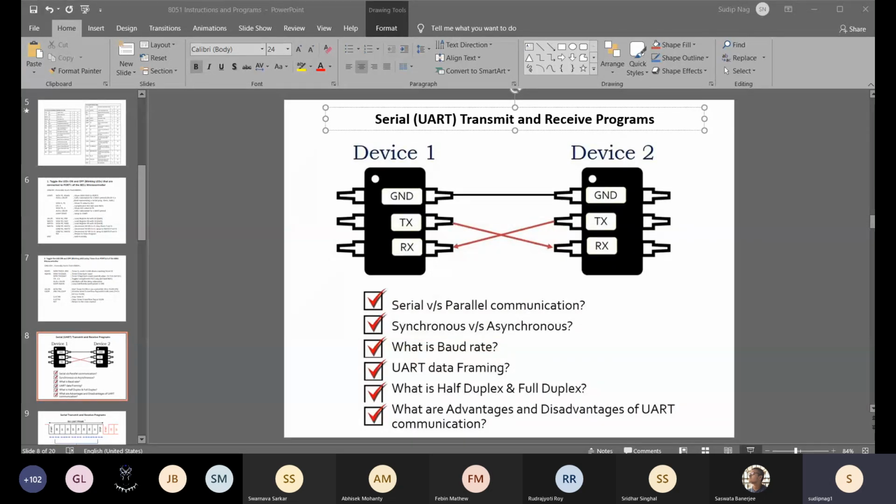Here we use an 8-N-1 UART frame example. There are different frame examples available for UART. 8-N-1 means 8-bit data, so the data width is 8 bits. There could be 7-bit or 9-bit or 10-bit data also. Typically 7, 8, and 9 are the three options here. Then no parity, so you are not sending any parity information about the bits. You're just sending the raw bits, and then one stop bit.